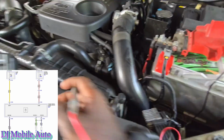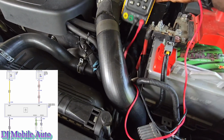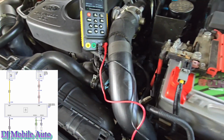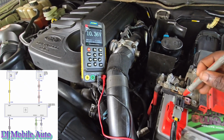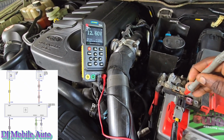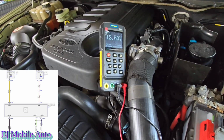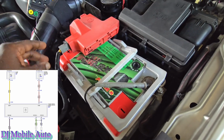I got my multimeter out. Let's press OK. Let's come right here. We're just gonna prop it right here so you can see exactly what I'm seeing. Okay, so I'm touching here. I'm getting battery voltage on both sides, so that's letting me know that the fuse is intact. And I'm gonna go onto the cable right here. I'm getting 12 volts also. So this cable right here goes straight down to the power steering, right?